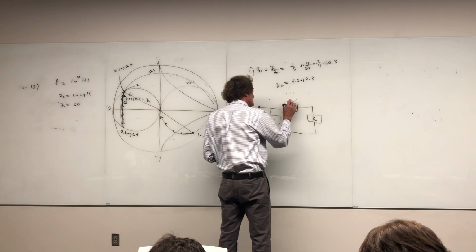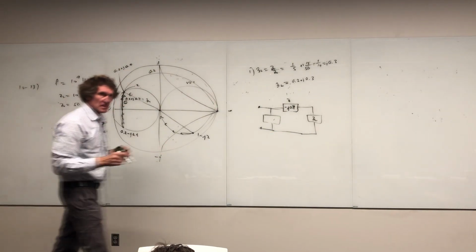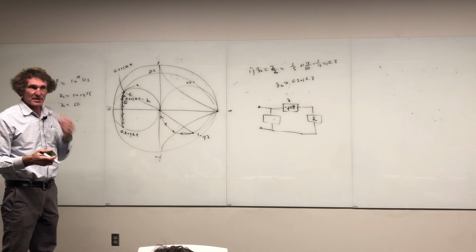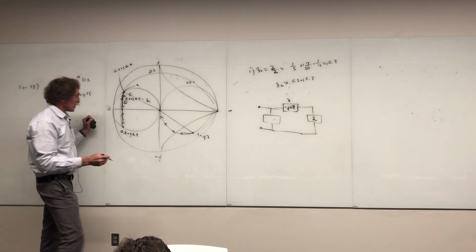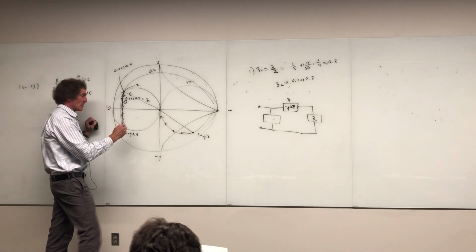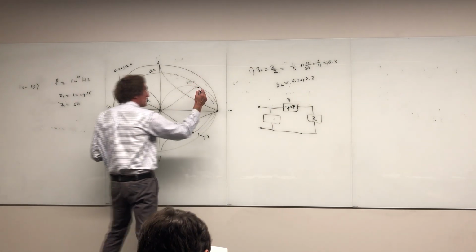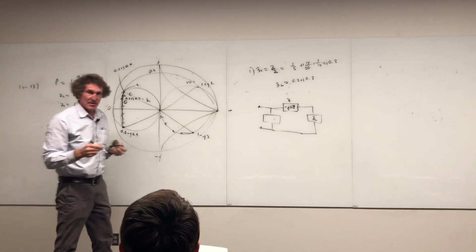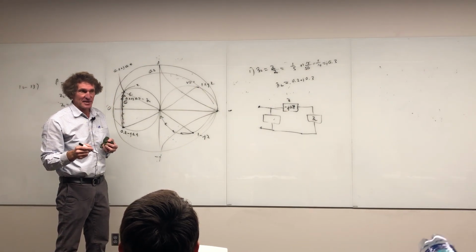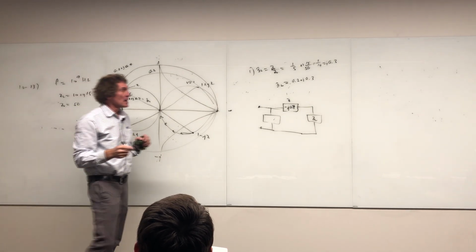And that is an impedance. So put a little z there. If you're not absolutely confident in yourself, put a z there until you get used to it. Now, at this point, we're down here, and we take 1 over that. We're going to go to this point, and that will be 1 plus j2, I believe. Check it out. That's what I got. Has to be. These are always conjugate points of each other.